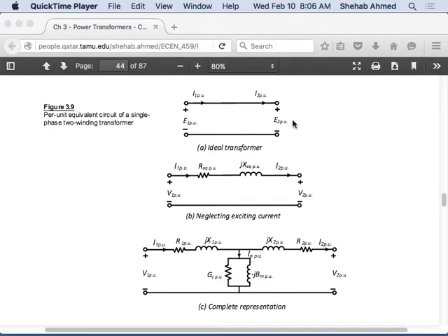So we looked from this side, and we were able to measure: we apply some voltage, a certain current will flow. Let's say you put a short circuit, for example, and you have a black box, like the Thevenin equivalent circuit, or a two-port network. You put voltage on one side and look at the current. It will tell you what the equivalent impedance is in this box, right? Same thing with the transformer when we look from the other terminal. So from both terminals, the impedance was the same, right? So we concluded that we can model that as a series impedance in line with our two terminals.